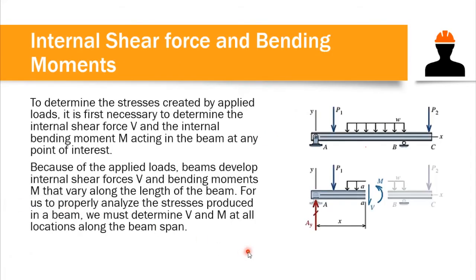Okay, our beam is being subjected to external loads such as this one: we have a concentrated load and we have a uniformly distributed load. Due to these loads, our beam experiences stresses on its cross section. The value of these stresses must be determined so that, as an engineer, we can have a proper design for this beam and look for an appropriate dimension that is capable of resisting these stresses.